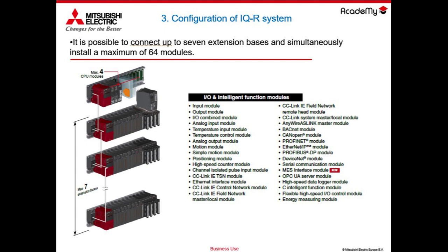If we take into account the rack of 3 slots, it means having a first slot, understood as the one immediately to the right of the power supply, which we will get to in a moment, plus 3 other subsequent free slots. So actually they are for a rack of 3, understood as slots on which CPU modules, smart modules or I/O modules can be housed: 3 plus 1.